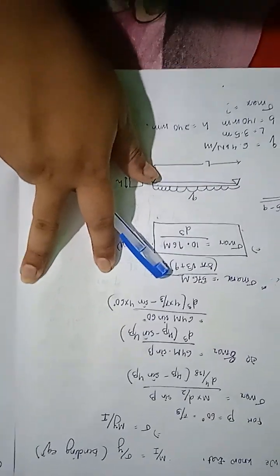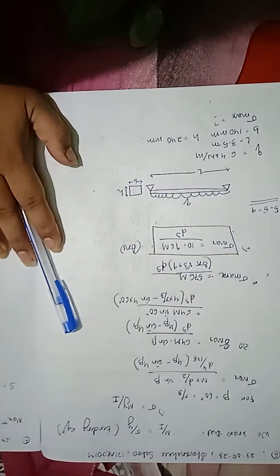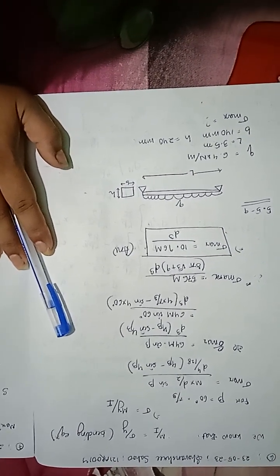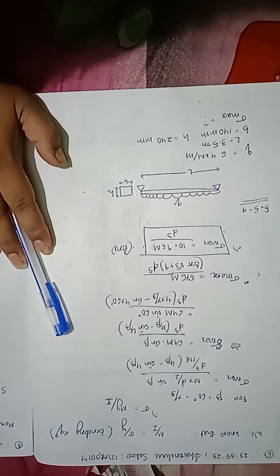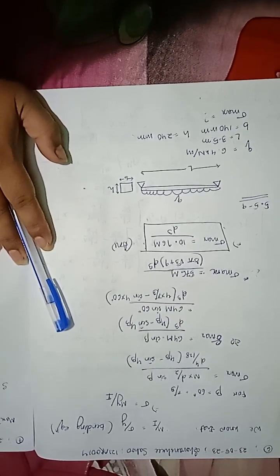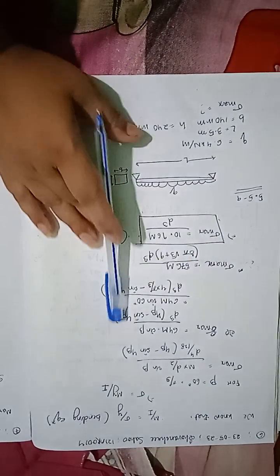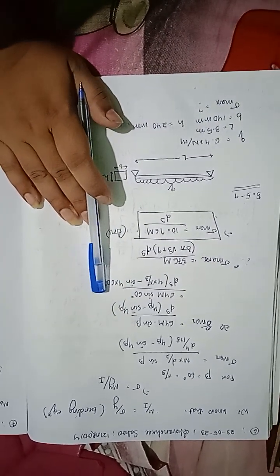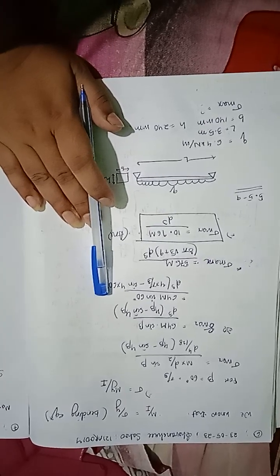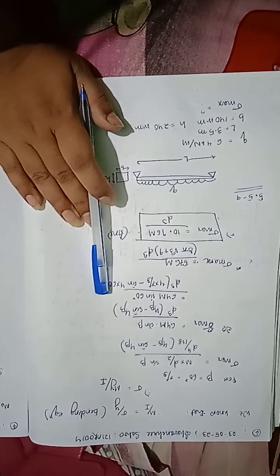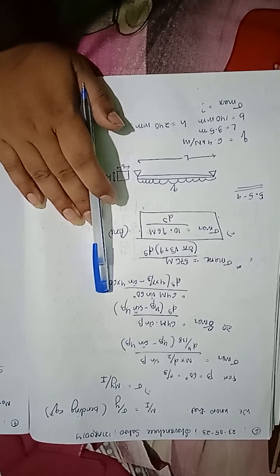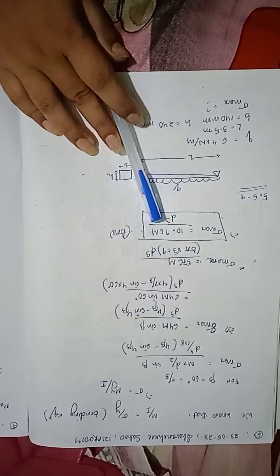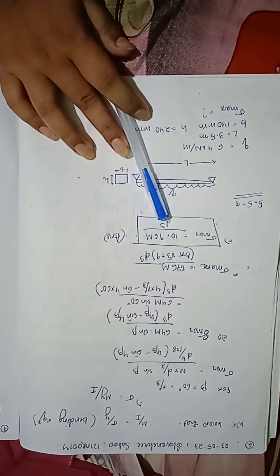So we know that M by I is equal to sigma by y, bending equation, which implies sigma is equal to My by I. So for beta is equal to 60 degrees, which is pi by 3 radians, sigma max is equal to M into d by 2 sin beta divided by d to the power 4 by 128 whole into 4 beta minus sin 4 beta. So sigma max is equal to 64M whole into sin beta by d cube into 4 beta minus sin 4 beta, and on solving we get sigma max is equal to 10.96 M by d cube.